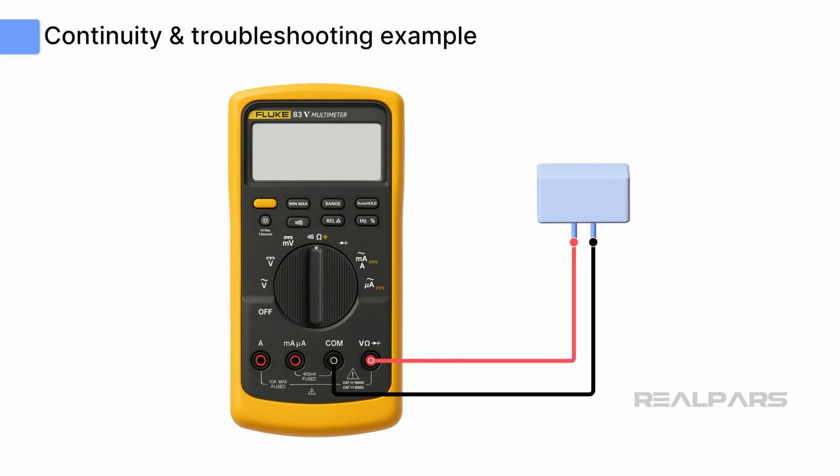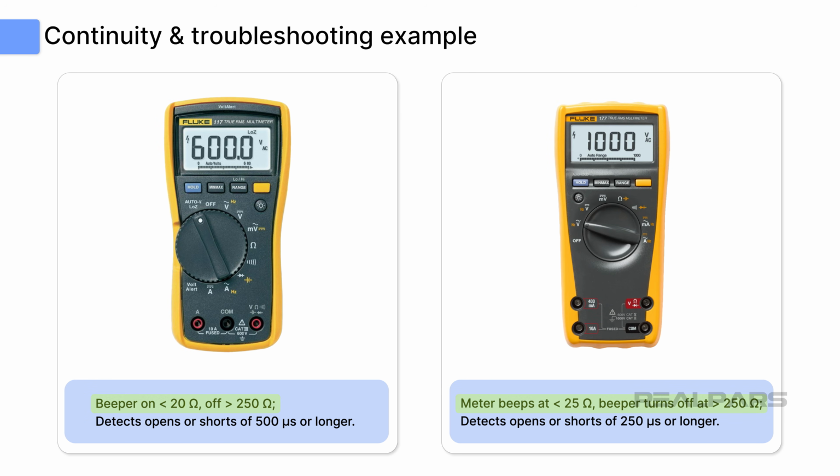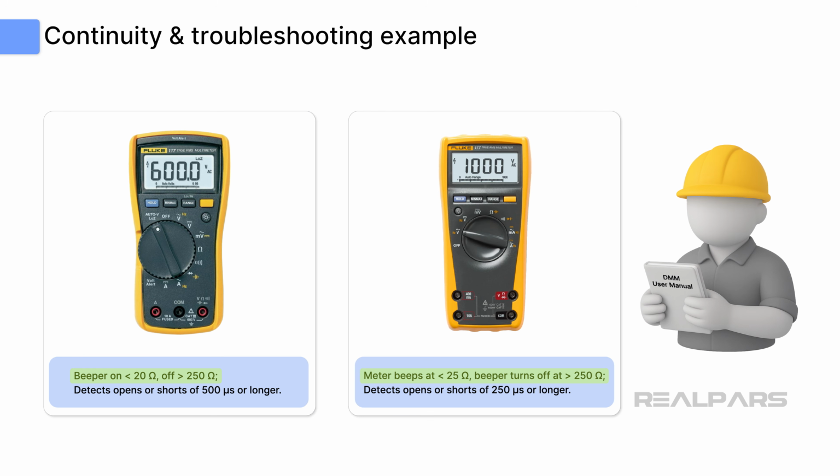Unfortunately, the beep only means that a complete circuit is present for current flow. The beep tells us nothing about the resistance of the switch. In fact, the multimeter may produce a beep up to a measured resistance of 50 ohms. We don't want a switch with a resistance of 50 ohms. In fact, most DMM specifications state a finite continuity threshold value at which the device beeps, depending on the range setting. When you have a few spare minutes, dig out the user manual for your DMM and see if you can find the continuity threshold value. If you can't, experiment with a potentiometer.